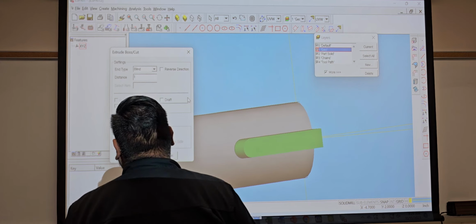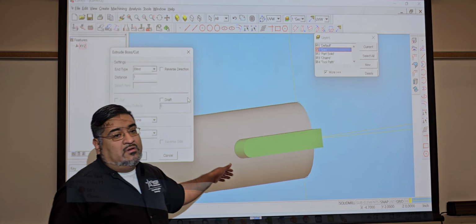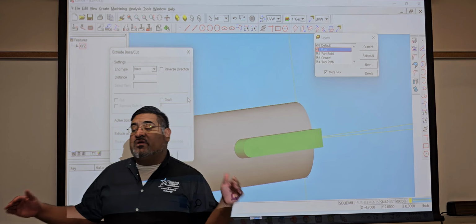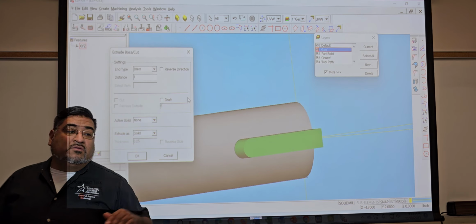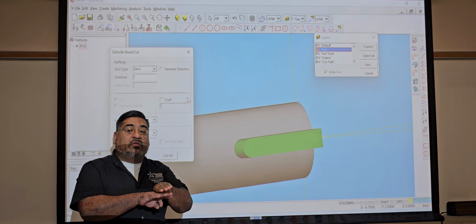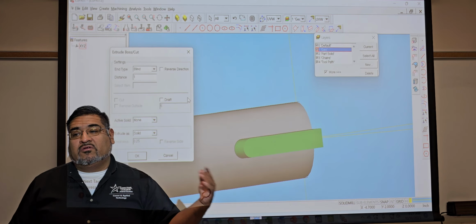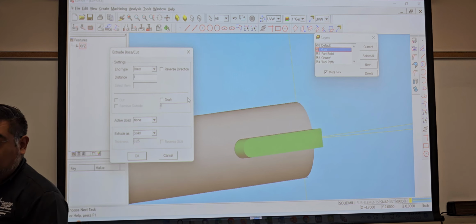All right, so the part is 3 inches in diameter. Theoretically, 1.5 should lead me to the center of it. But since we're going to extrude everything on the same planes, from the top and the bottom it's the same plane. Since we're going all the way through, we could go a little bit further just to make sure there's nothing down there. That's center plane.